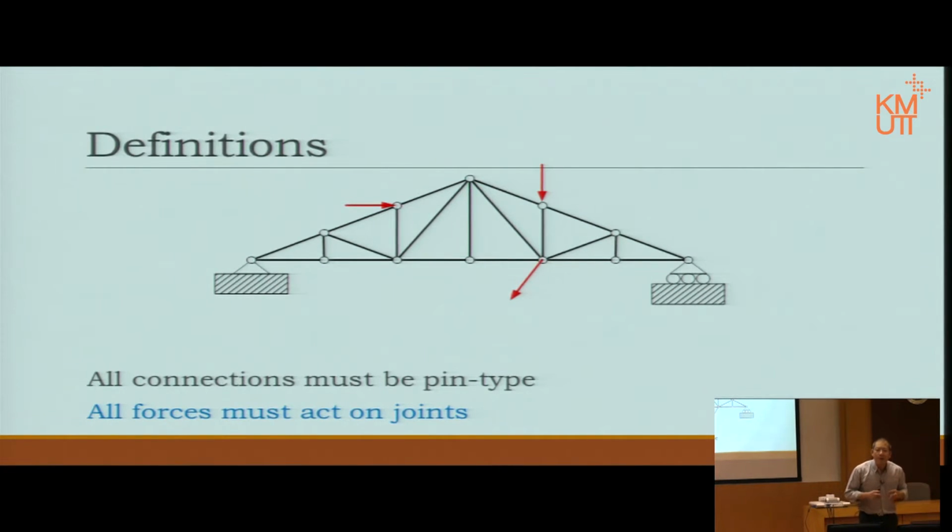But when we calculate, we have to make sure that the weight of the structure is very light compared to the weight it has to carry. If the weight of the structure is so small compared to the total weight it carries, then we can ignore it, or say that it has minimal effect, very little effect. Not theoretically correct, but in practice it is good enough.